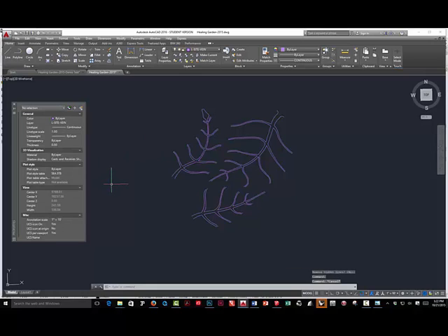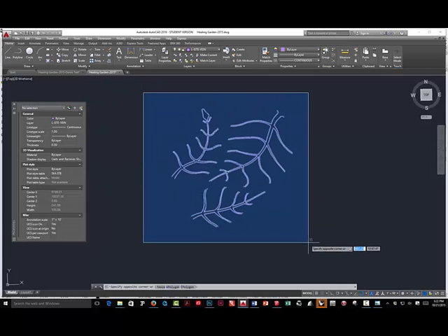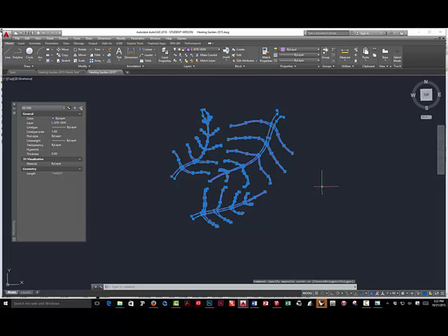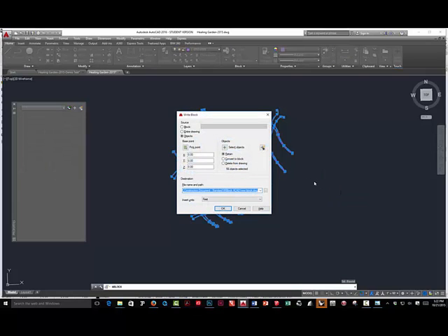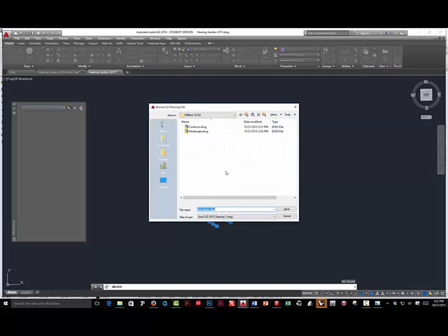As I said, otherwise when you bring it into SketchUp, it understands the elevation. So one end will be at 0, and one will be 1,000 feet off the ground, and that's not what we need to turn into a surface. So I'm going to select these and do a W block. Again, all this is doing is writing these things out, and that's the reason why we're using layer isolate, because we're not going to get other things. If you just hide the layers and select across, you may end up exporting things you don't want, because it's like SketchUp, it doesn't turn off the geometry, it just makes it invisible.